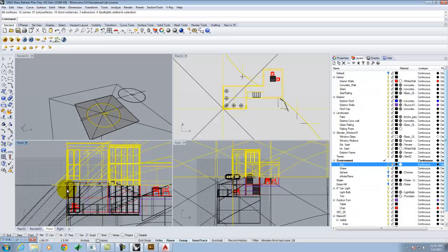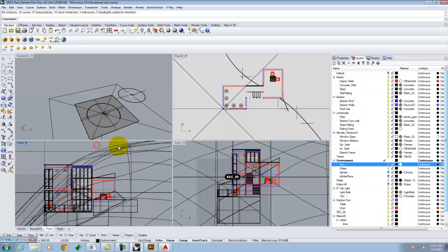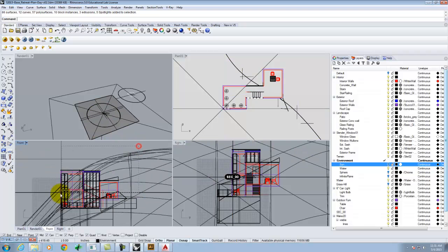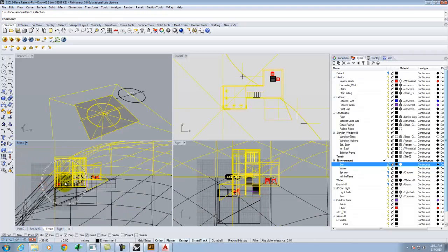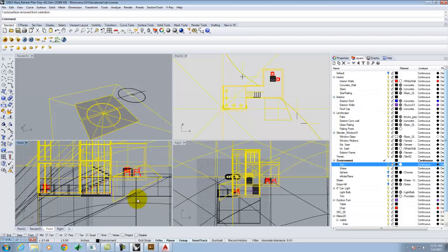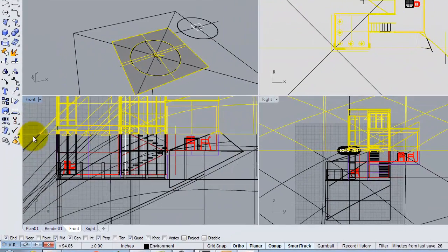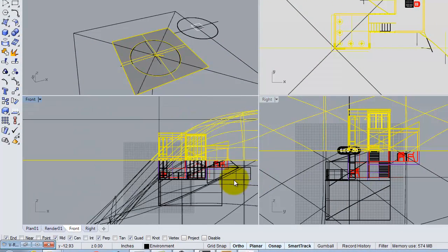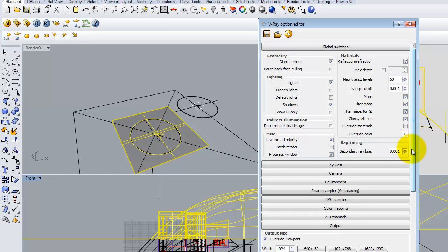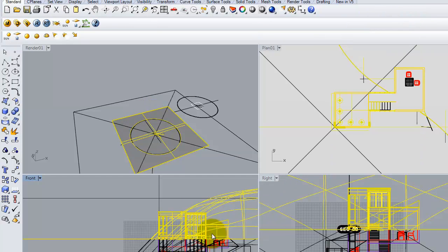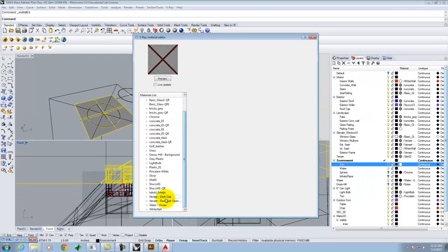like that, right down to where, oh, looks like I didn't quite get them all. There we go. So I got all of those objects there. These are going to have a see-through material applied. So instead of having my override on, we'll uncheck override materials for now, and I'm going to apply the see-through to these particular materials. So I'll go to materials, I'll find my see-through, which is right here.